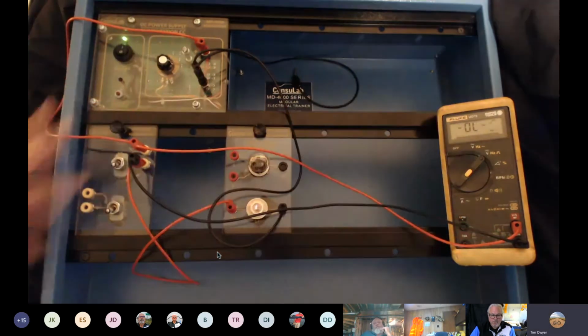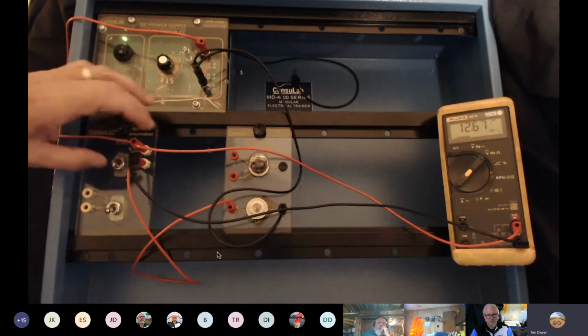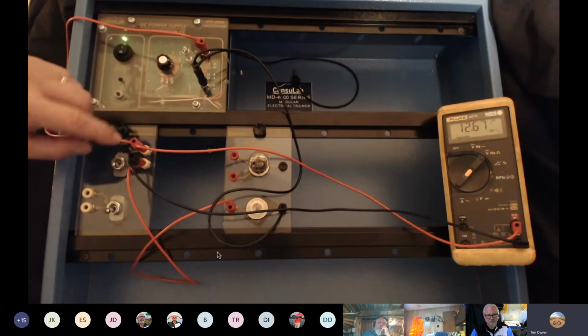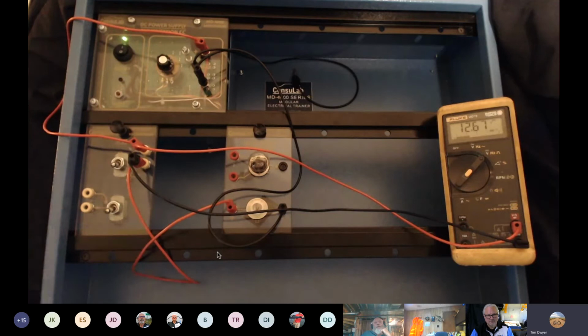Well, okay, then right there, we're getting a 12.67 reading. Is that a voltage drop, or is that? No, that's the correct reading because the circuit is through the light bulb. So I didn't see the. No, that's okay. I had a big discussion with Vince about this one time, because I said, how does it know that it's not reading backwards? How does it know it's reading across the switch or going the other direction? How does the meter know? And he said, the meter doesn't know anything. The meter just knows the difference between the two.